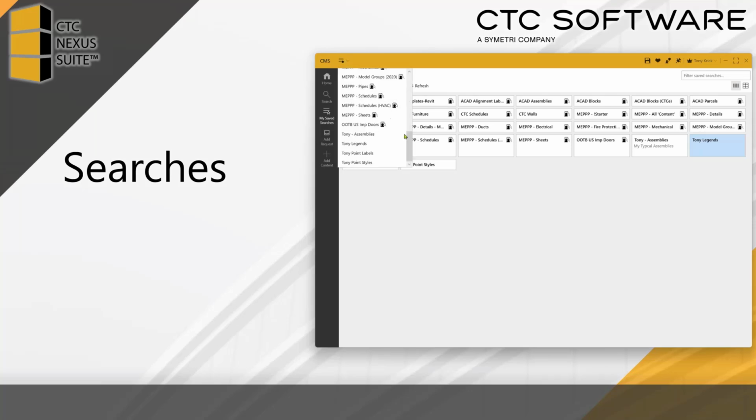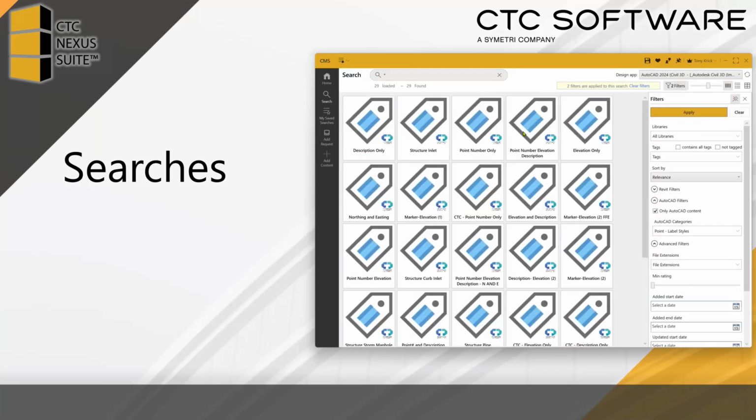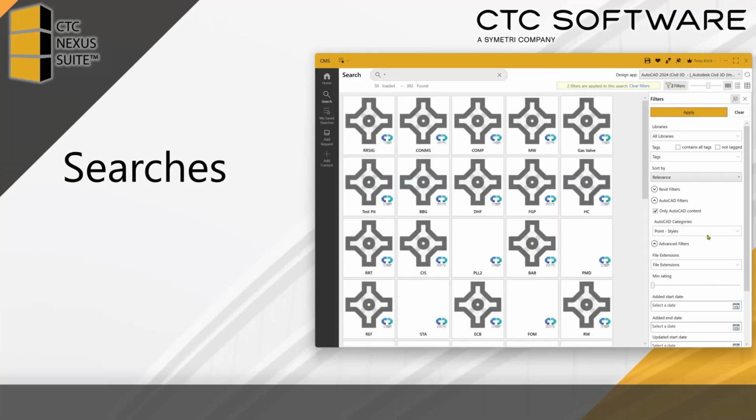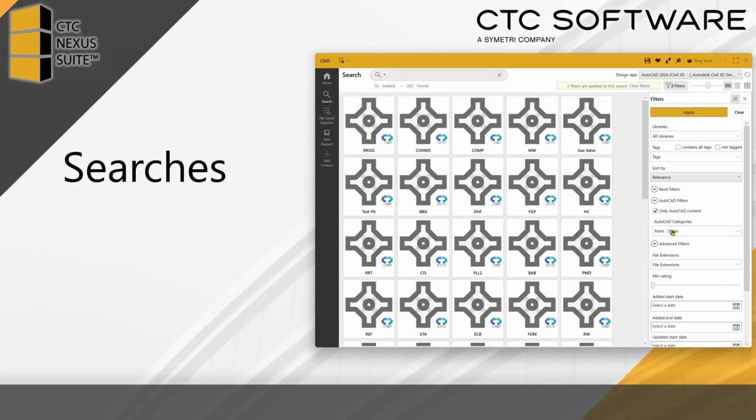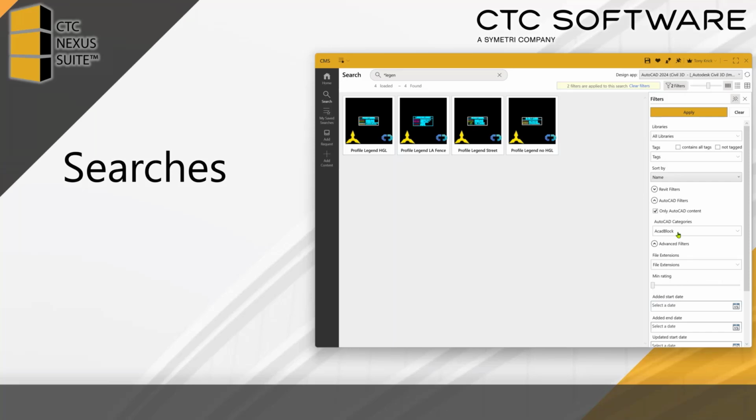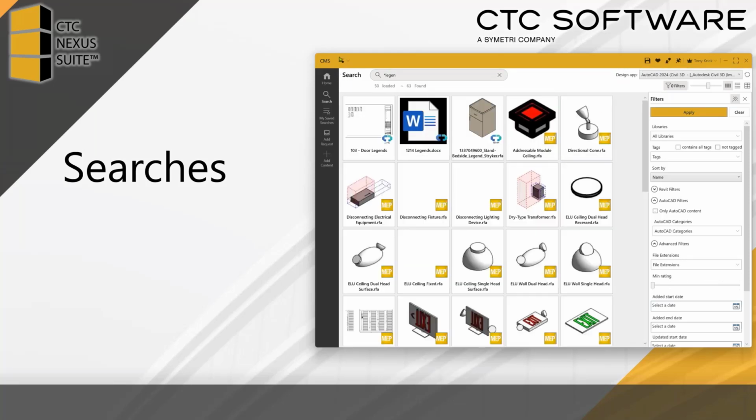We have the same thing. So we can see the same thing up here. So if I click that, not sure why it wasn't working in the other pane, but if I click that, now I see all my point styles, which we kind of searched for before. But if you notice, these filterings have changed over here. So if I click another one, we'll see that it's going to only see that. Okay, so this is what it's looking for in that blocks, which I can turn on and off here, clear this out and apply. I can also clear my search this way and back to everything.